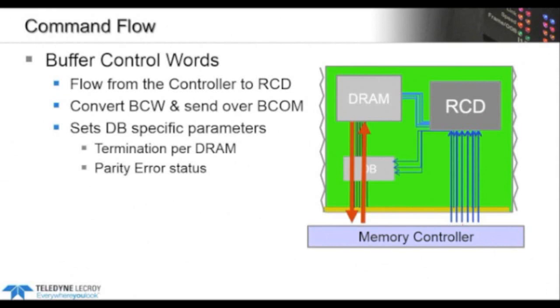Okay, so normal commands, your reads, your writes, your MRS, they're going to flow directly between the host and the DRAM. So that's one point that shouldn't be lost on anyone. This is, again, how these LRDIMMs are going to decrease your loading and give you the higher capacity that they're promising. So again, pretty sophisticated, no doubt about it.